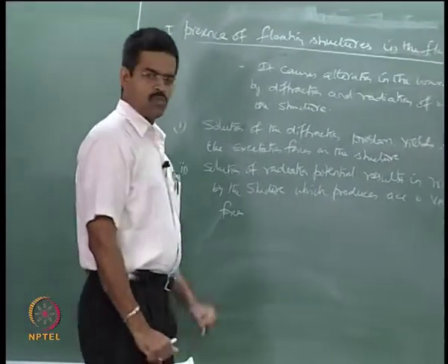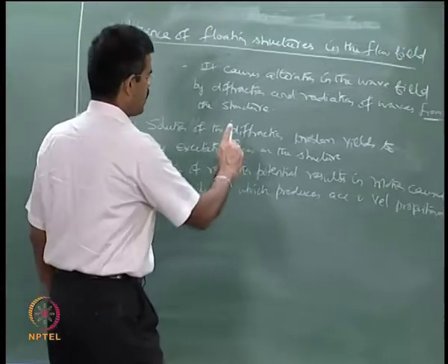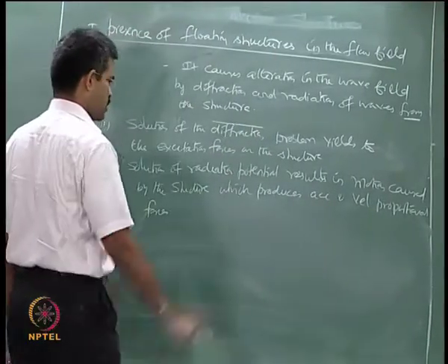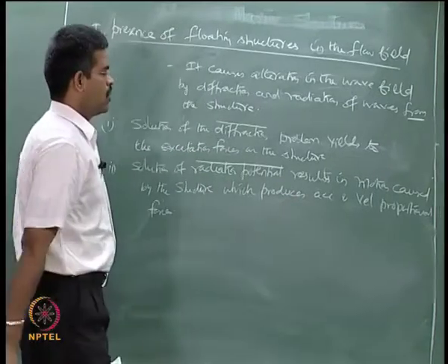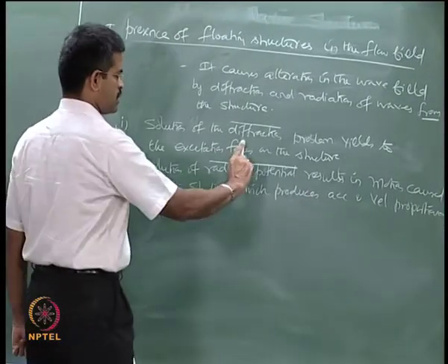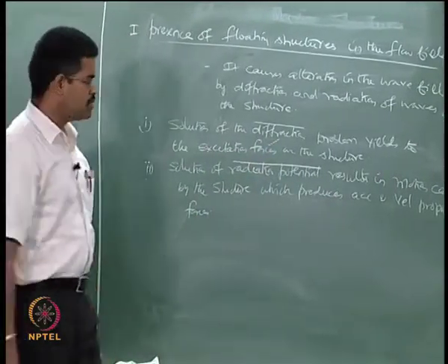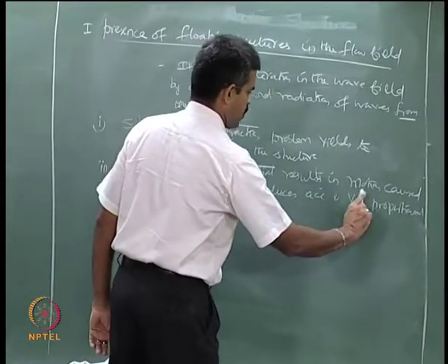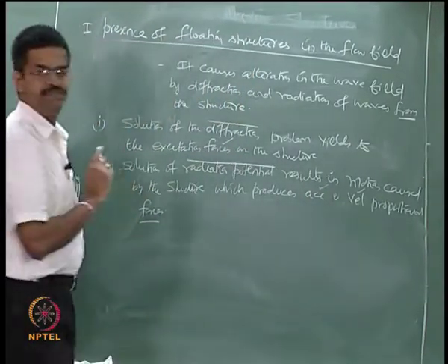So, this problem has two kinds of solution, one is the diffraction potential solution, the other is the radiation potential solution. One yields the excitation force, the other yields the acceleration and velocity proportional forces.